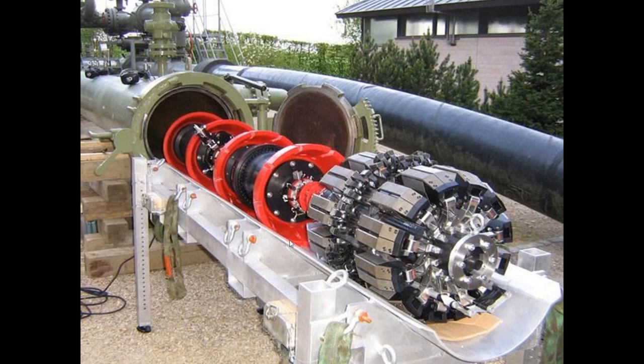So this is one of the very good technologies people are using in the current industry. Once they start this machine, it is so intelligent that at every 1 meter precision, or every half meter or every 100 mm, whatever precision we decide, it will keep on giving the thickness, because in the sea, corrosion will generally happen. Because of corrosion, holes will happen, and because of holes, leakage will happen.